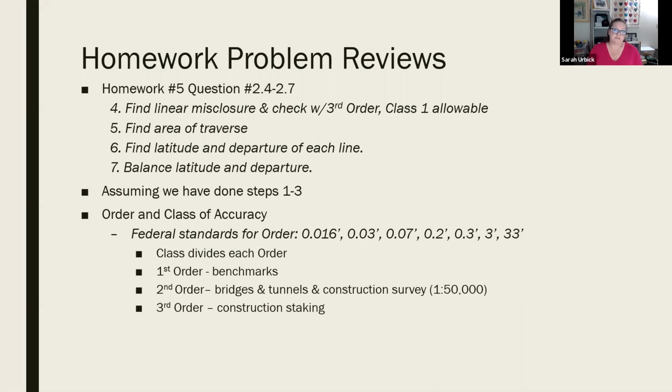Construction surveys. Now, what's interesting here is that construction surveys are typically second order. That's going to be when the surveyor goes out and marks it. It's going to be a licensed professional. Construction staking is a third order level of accuracy.